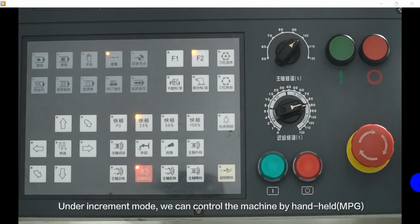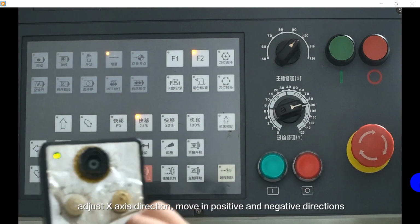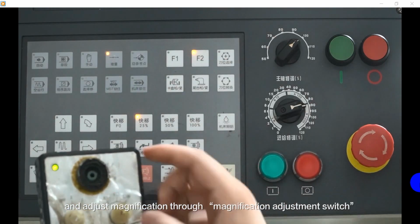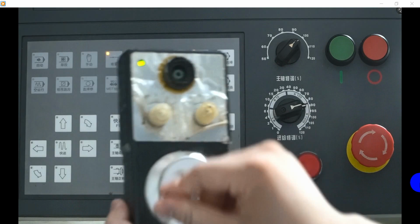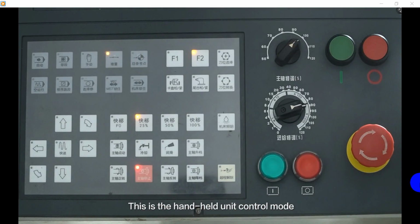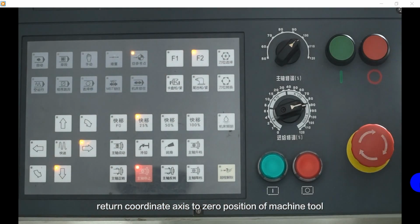Under increment mode, we can control the machine by handheld. Adjust the axis direction, moving in positive and negative directions, and adjust the magnification through the magnification adjustment switch. This is the handheld unit control mode. Click Return to the reference point to return the coordinate axis to the 0 position of the machine tool.